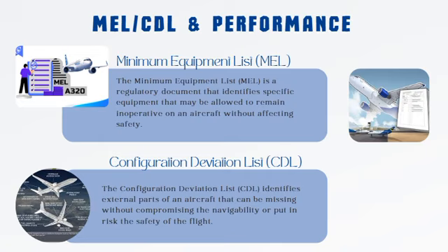Each item listed in the MEL includes restrictions, maintenance actions, or operative procedures that must be adhered to when the equipment is inoperative. The MEL's purpose is to ensure continued safety while offering operational flexibility, helping to reduce delays and cancellations due to minor equipment issues.